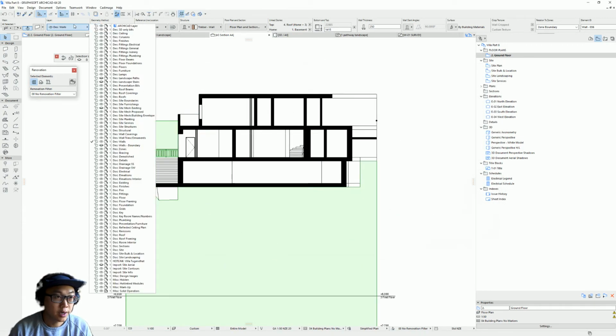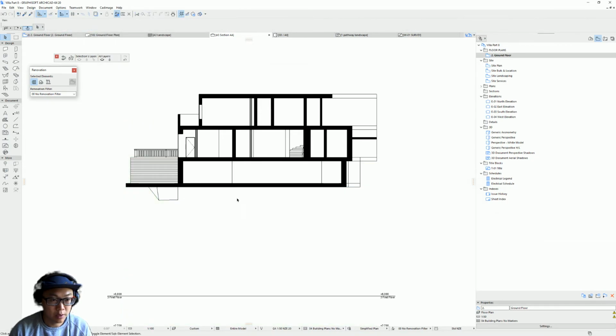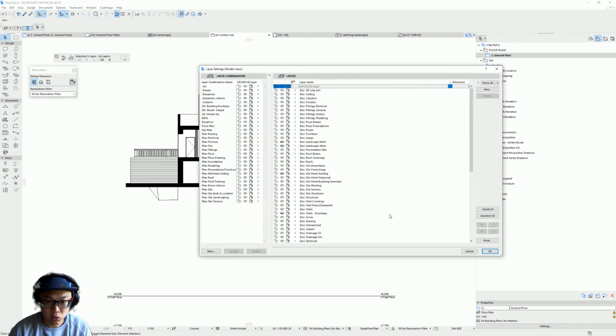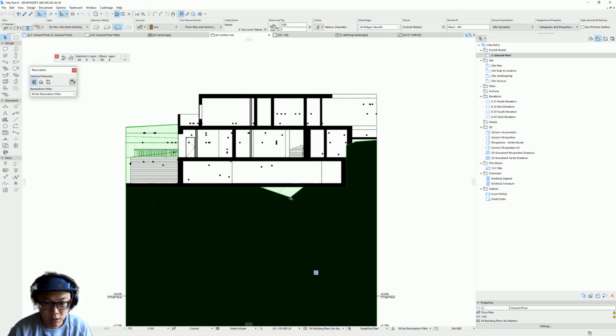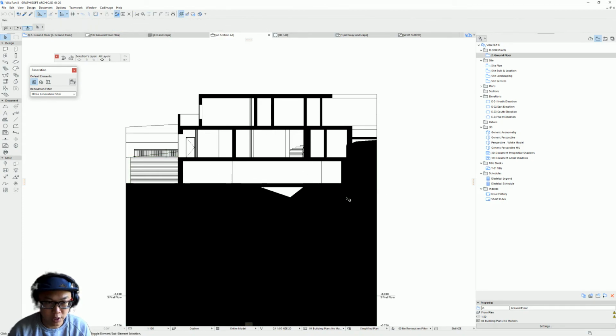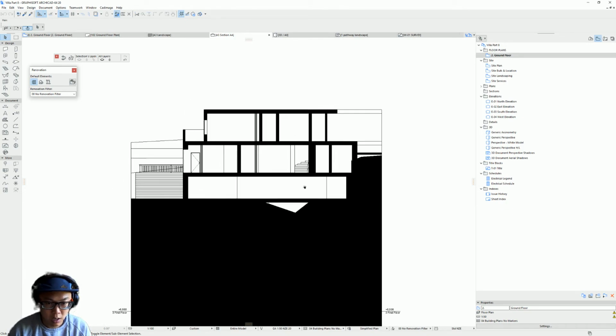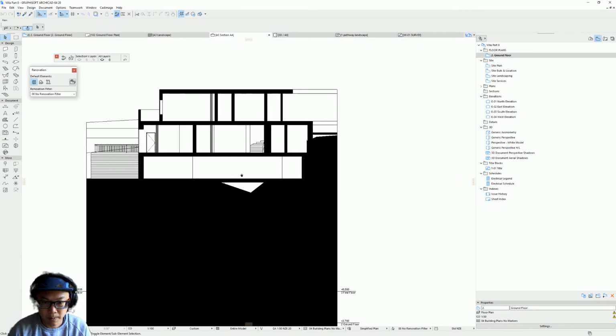Select that wall here and put it in the wall boundary. So now it's gone. I think I'd like to see the site mesh. Press OK. As you can see, there's a dip here. I guess that's the mesh that I need to edit again.